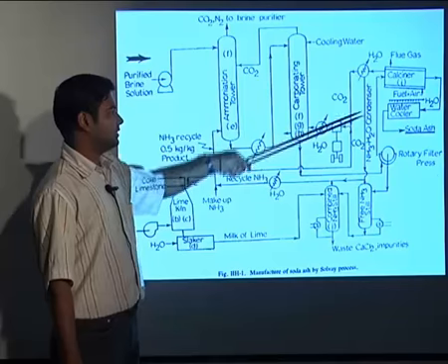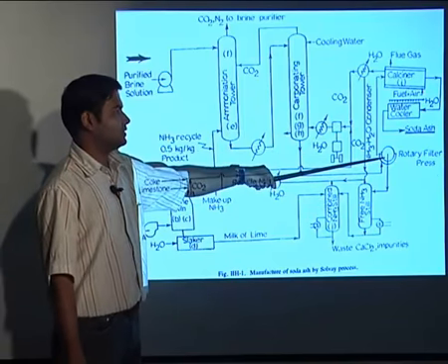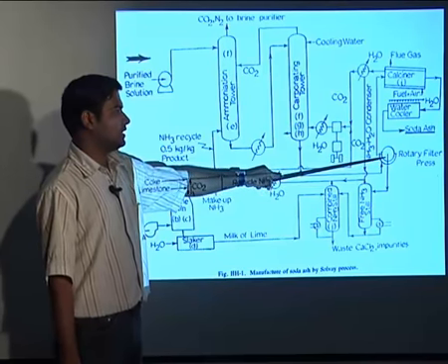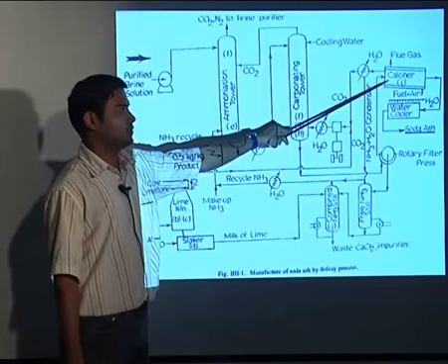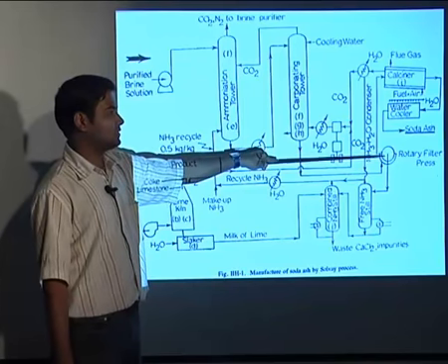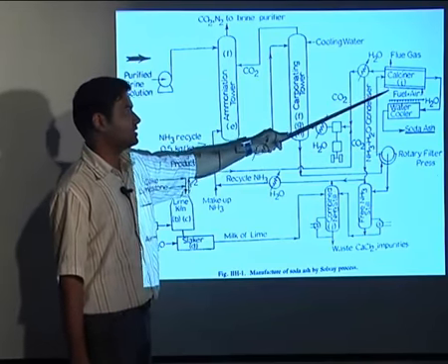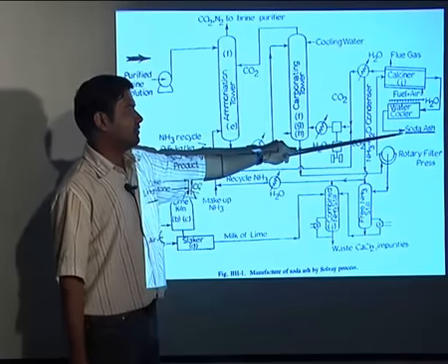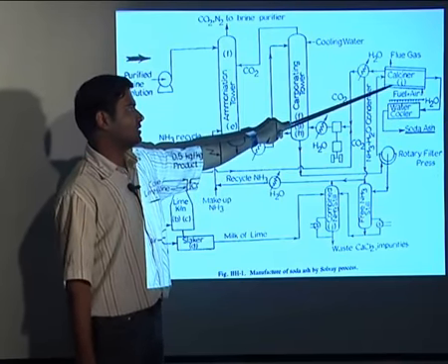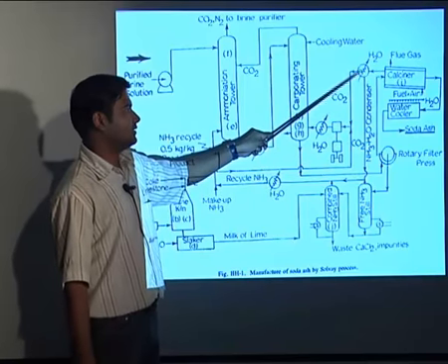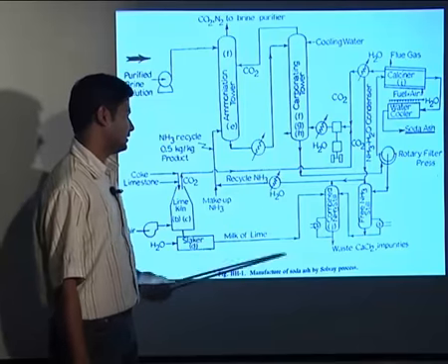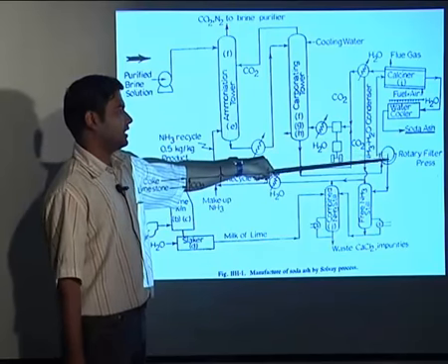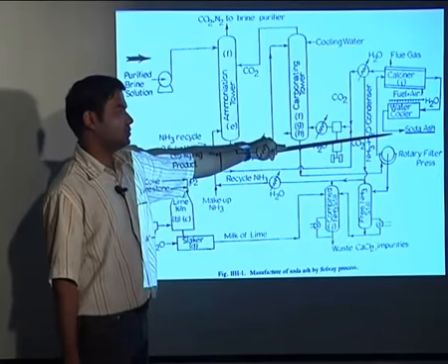Then whatever the products which are forming over here, that will go to the rotary filter where the soda ash and the water solution or the filtrate will be filtered. Then we are sending it to the calciner where the NaHCO3, whichever is formed here, will be decomposed to give the soda ash, and then we are adding water and then we are cooling over here and it is dried and we can send it as soda ash. And whatever the other gases that are sent out and whatever the heat which is produced over here, that we are recovering back. So you can see the first one is the reaction with the ammonia and the carbon dioxide, and then we are getting the bicarbonate which we are calcining to have the soda ash over here.